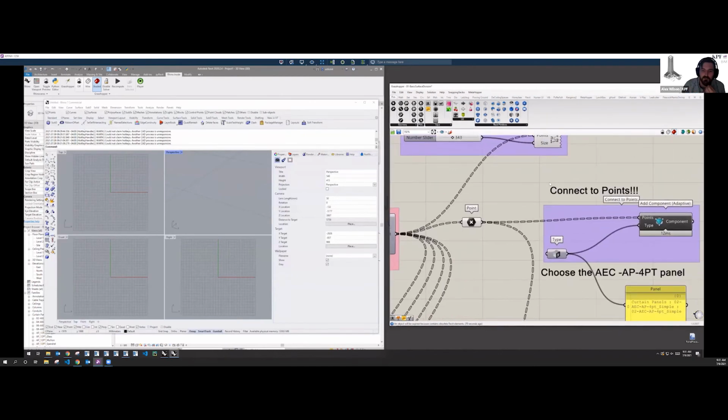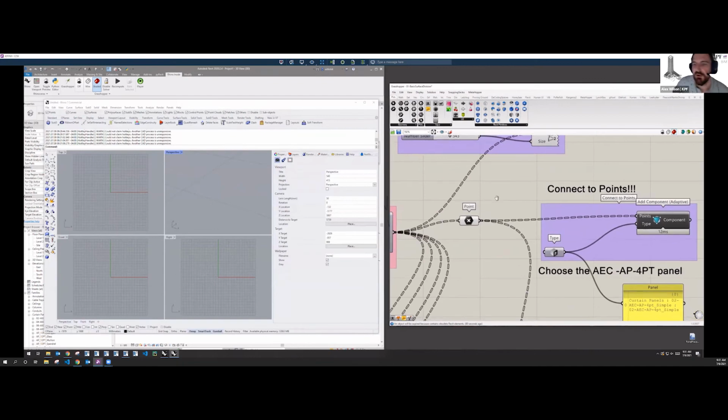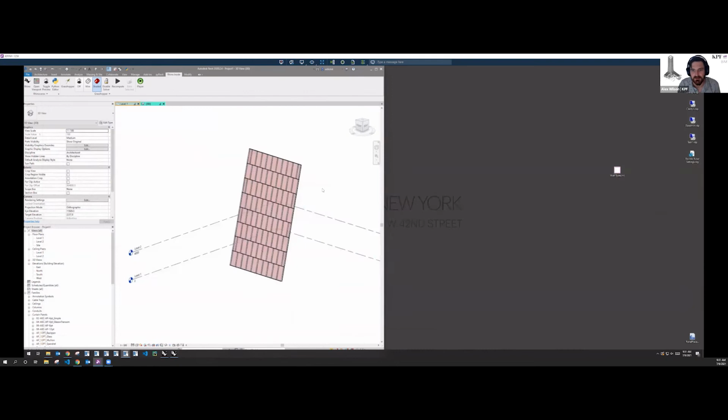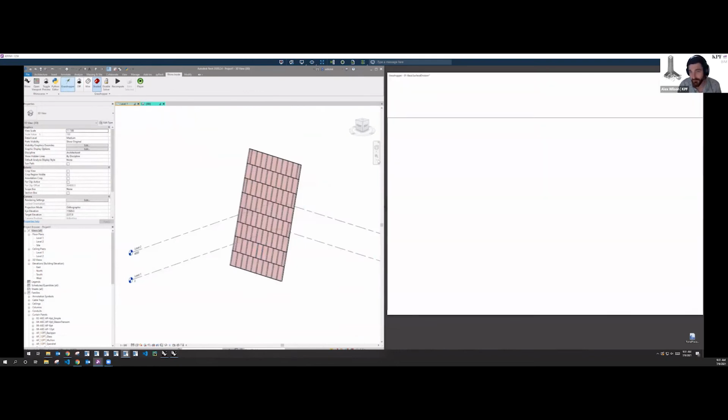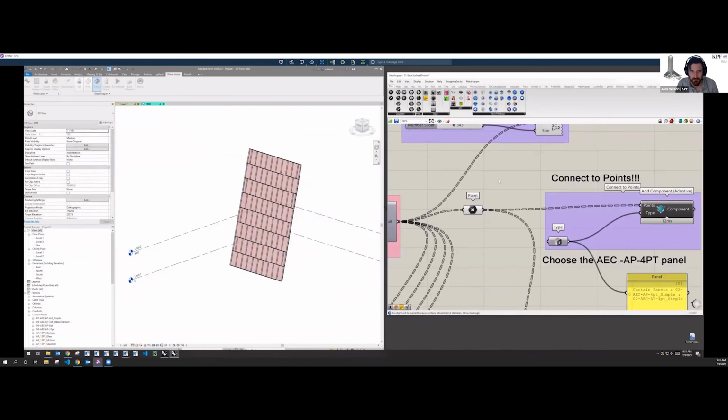So one quick thing to bring up about the element binding and why that's an important thing to note is that Grasshopper flows from left to right, as most visual programming software does. The reason that this is super important to understand is that Rhino.Inside doesn't use the baking method that Grasshopper does.